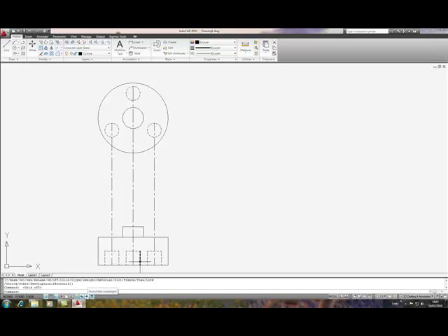Show stroke hide line weight. So if I click on this, and hey presto, you can see what the line weights actually will look like on the final plotted drawing. You don't normally leave this selection on if you're continuing to work on the drawing, if you're doing some further editing or finishing off. It is just meant as an indication.